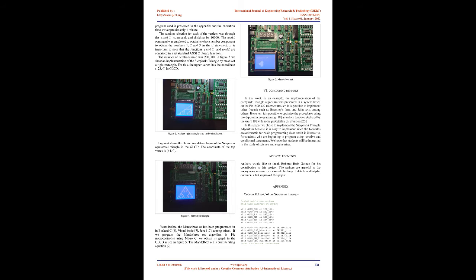The PIC 18F family offers many advantages in its performance. They offer numerous advantages, such as low-cost efficient solutions for general-purpose applications written in C that use a real-time operating system, RTOS, and require a complex communication protocol stack such as CAN, USB, among others. PIC 18F devices provide flash program memory from 8 to 128 KB and data memory from 256 bytes to 4 KB, at speeds from DC to 64 MHz. 13. For example, some characteristics of the PIC 18F